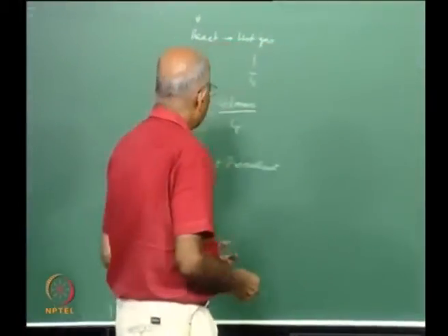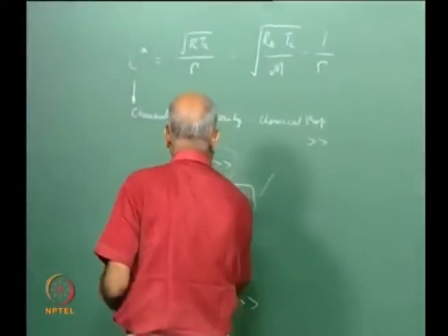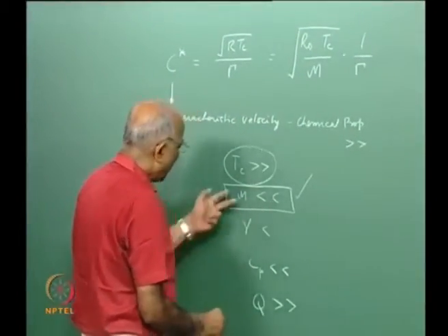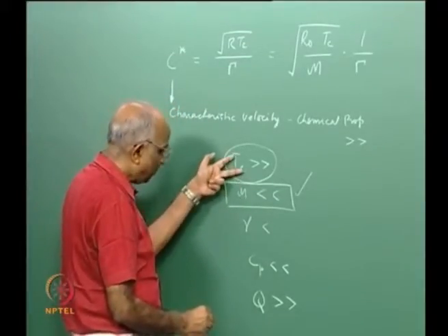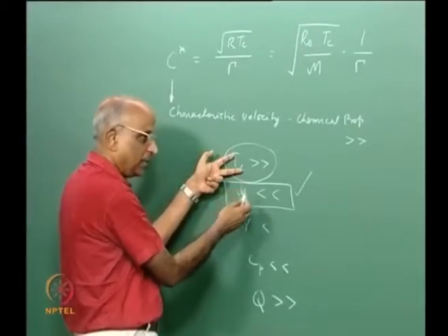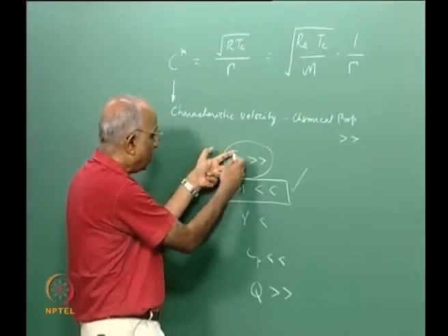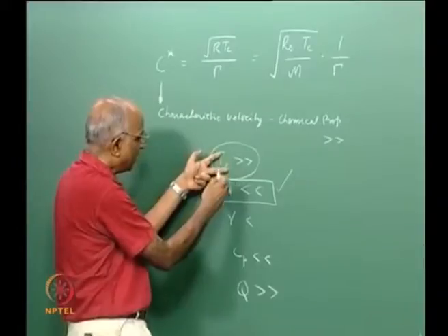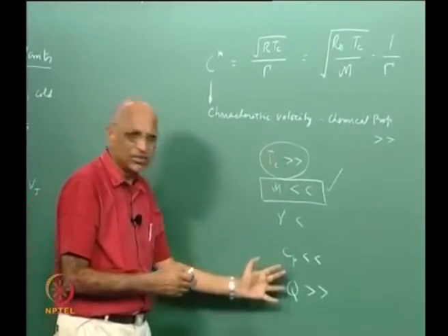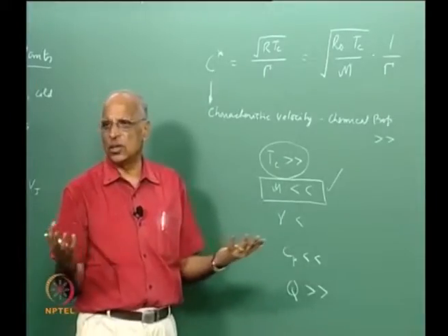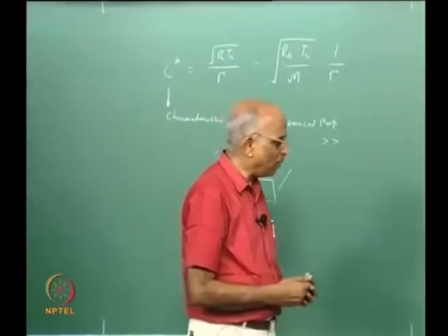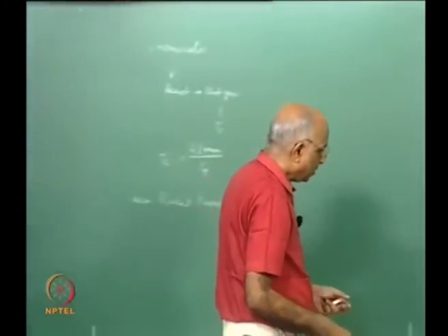Therefore, now we tell ourselves, well, I have looked at one step of it, from the molecular mass point of view. Let me take a look at the next step, maybe from the temperature point of view, whether I should have some of these elements or what should be the composition of gases such that I get a high value of temperature. Maybe if you go through this, half of our work in choosing a propellant will be over. Let me come to the second part therefore. Let us take a look at the specific heat.